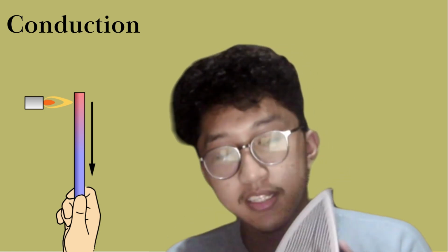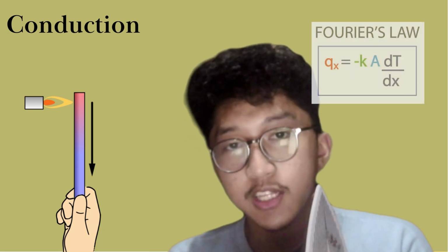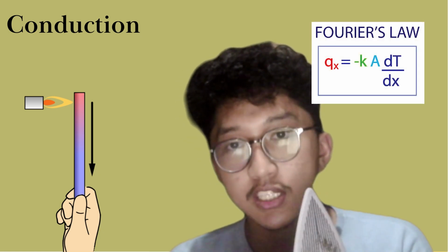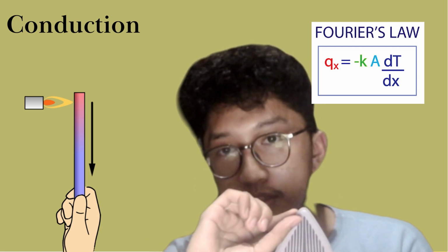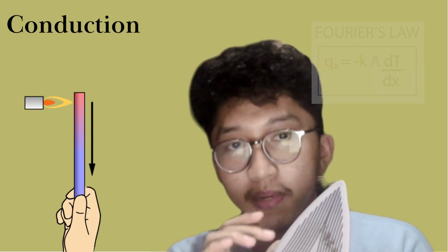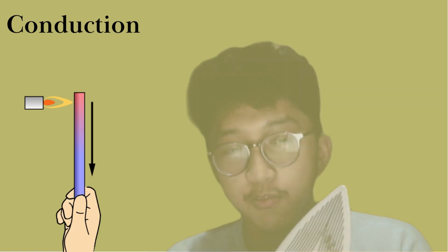We can see the plate here is also not thick, because the rate of heat transfer by conduction is inversely proportional to the length required to travel, in this case, the thickness from the top to the bottom face. So a thick plate would take longer before we can use it for ironing.